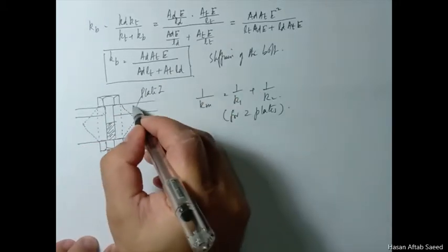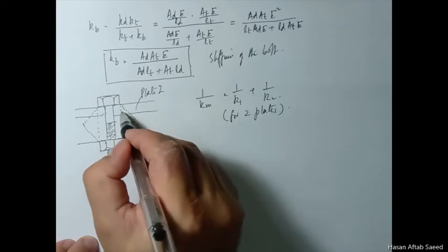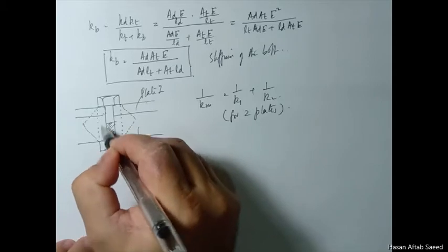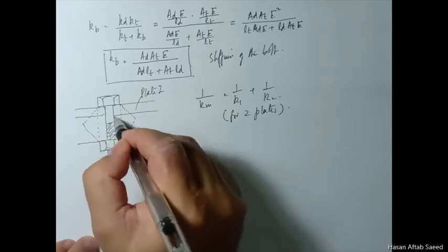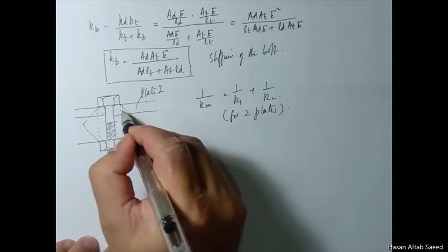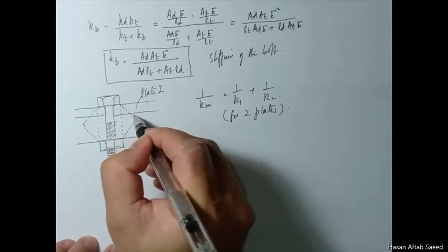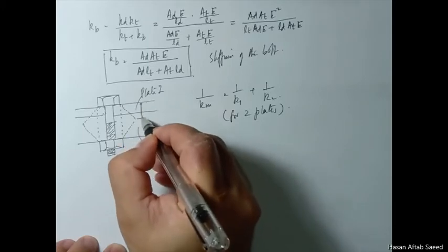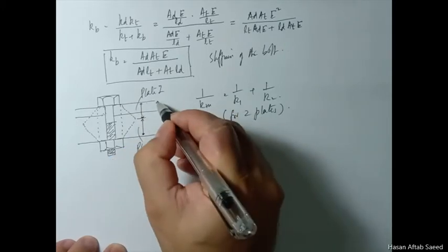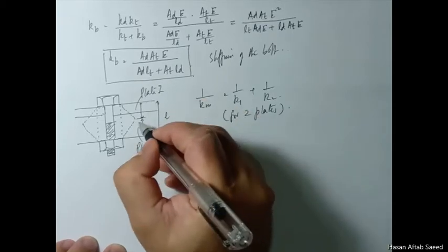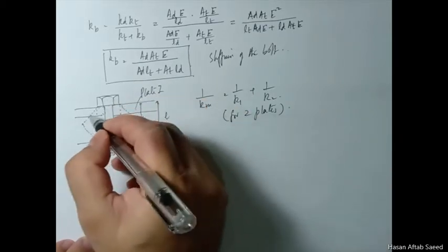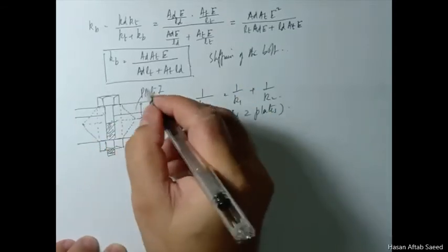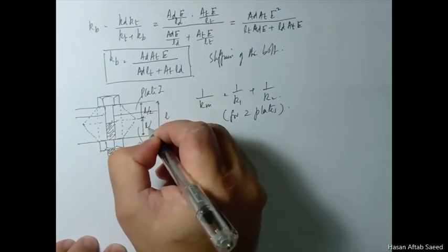Obviously, these are connected together, so the compression effect is not directly under the head of the bolt and over the head of the nut, but they slightly diverge as you move away. Now this sort of a situation takes place, and if this is the total grip length L, then these two meet at a distance L over 2 and L over 2.